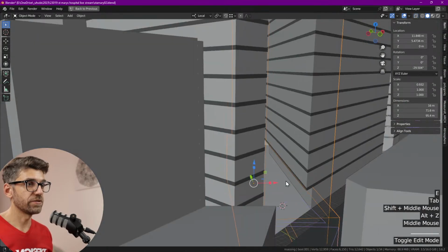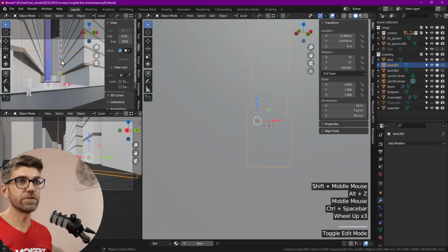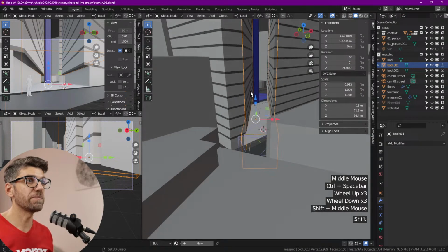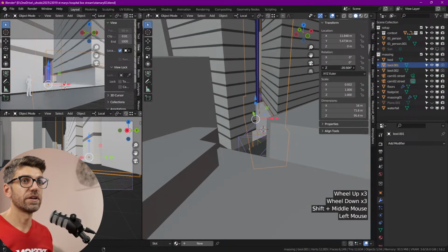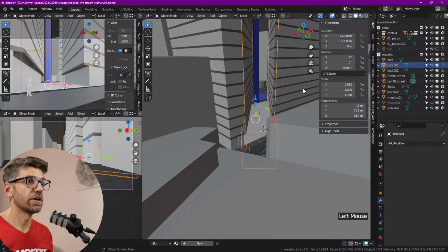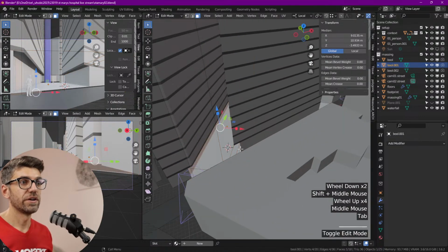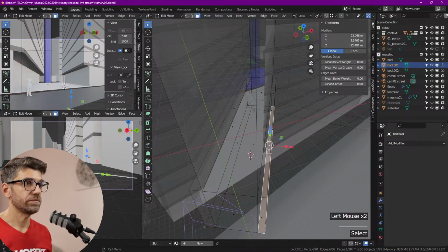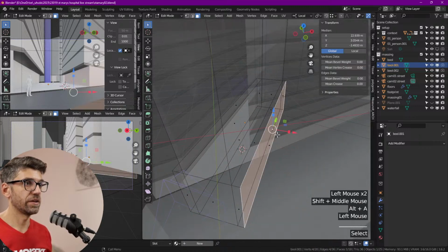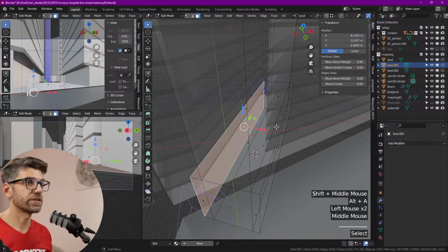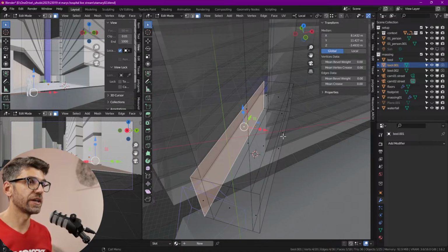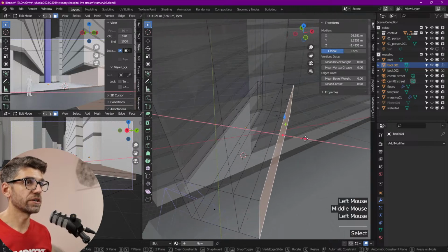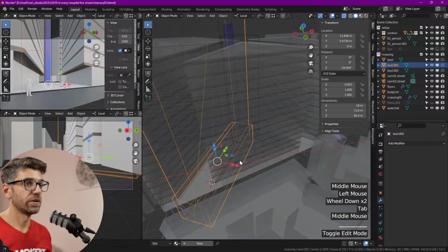Okay, and you see, just like that, if we go back to our views, now we've stepped this back in such a way that if we rotate, it stays with it. So it's really nicely aligned. Might even go 3 meters. So let's move this an extra meter out. So -1. And why did I type -1, you might ask? Because look at the direction of the arrow that's pointing. It's in the negative direction. So let's click here, click drag, and +1. Okay.